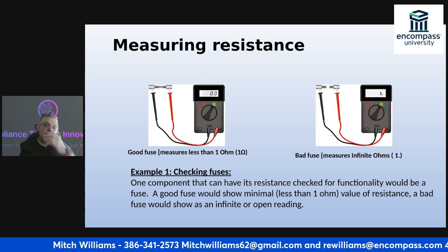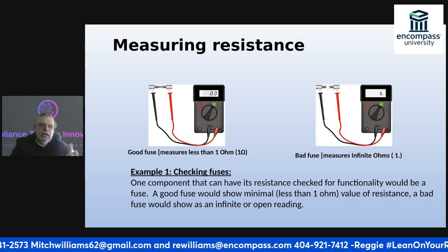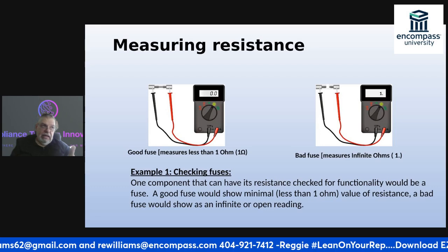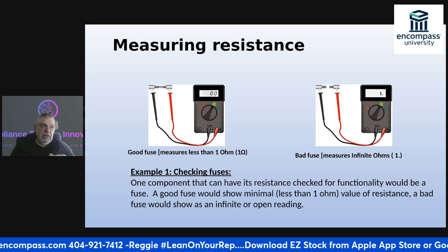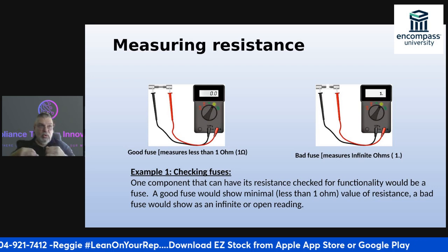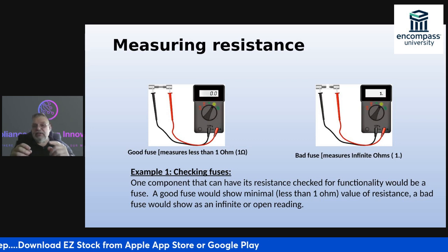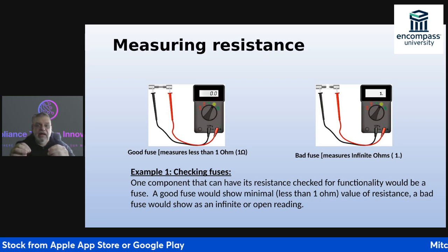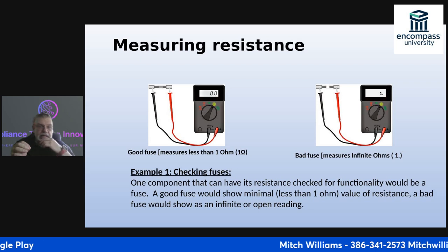So measuring resistance. What I always do, if I have a fuse in this manner, is remove it from the system and check it.